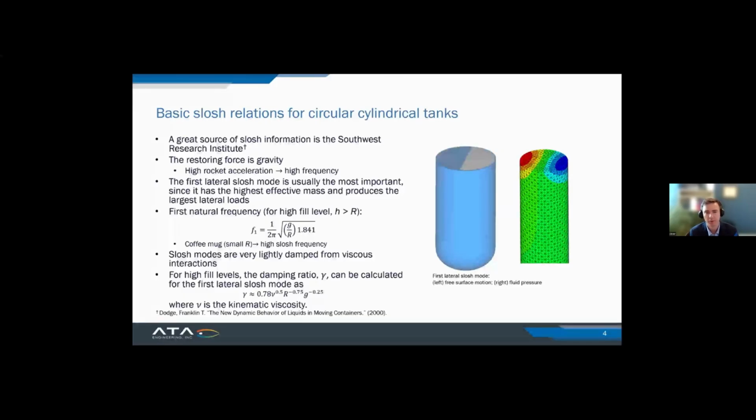I don't know if you're solving this with Vibrata, right? You just say, okay, modes between 0 and 2 hertz have 0.1% damping or whatever you calculate for this equation, and then anything else, it's your structure. You can define your regular structural damping however you want to. But there's no material property that you can define that would automatically give you these damping results. I know some people have written their own DMAP to get around that, but there's no inherent Nastran way of dealing with this.